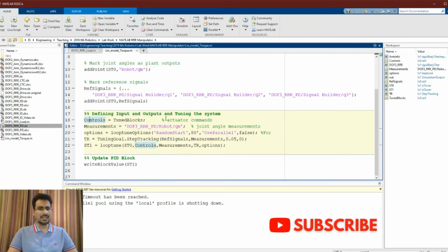In the second section of this code, I have used a bit different terminology so that it can better relate with the control system. So I've named the tuned blocks as controls and the robot outputs as measurements. So these are the measurements, that is the robot joint angles, and these are the outputs or the controller output that we are going to feed into the robot.